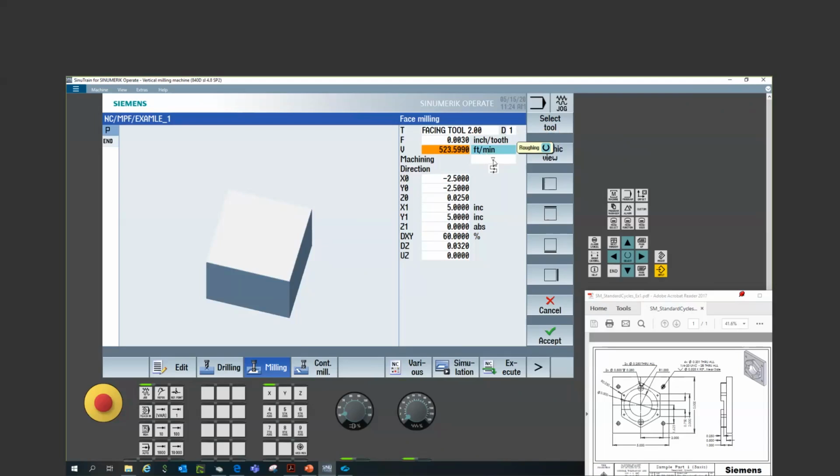And then when we get to machining, you have the single diamond selection, or you have the triple diamond. So single diamond would be for roughing, and triple diamond would be for finishing. So we're going to rough it, and then we can select our cutting strategy. So here we have a Y step over in a unidirectional cut. If we were doing a bidirectional cut, you can see it rapids back. And then if we wanted to do this step over in the X direction, either bidirectional or unidirectional, we have all those choices. So we'll select the bidirectional.